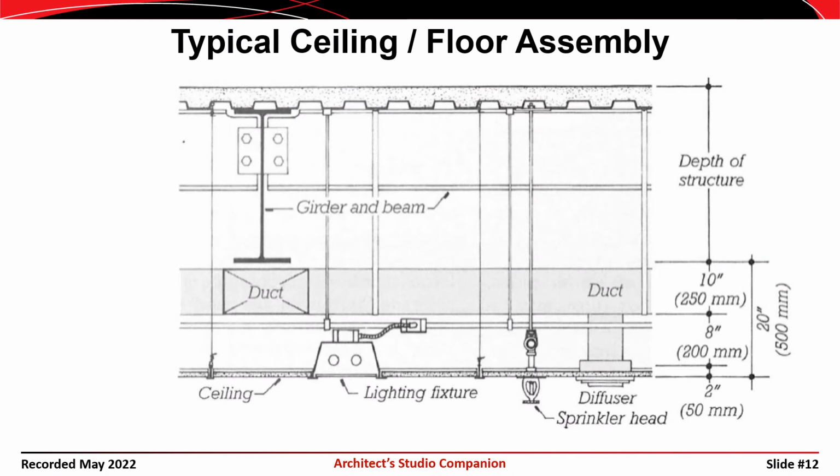Okay, it's not just the weight of the floor, though. There are also superimposed dead loads or super dead loads that include the weight of, say, lighting fixtures, ductwork for the air handlers, sprinkler assemblies, and then, of course, the weight of the architectural items like the ceiling panels and things of that nature. That all has to be supported as well and is considered part of the dead load.